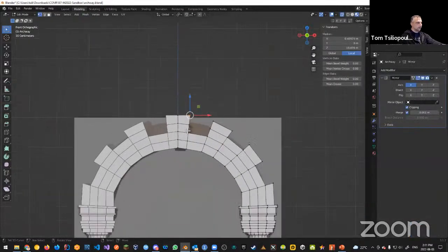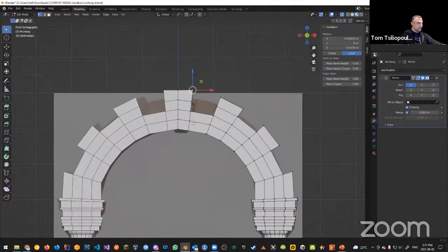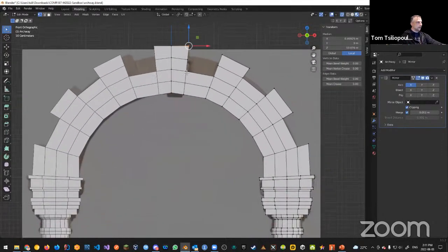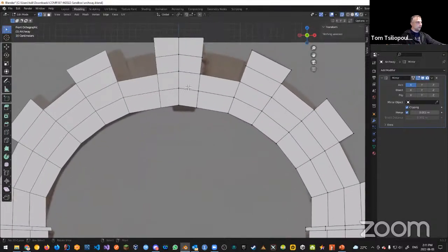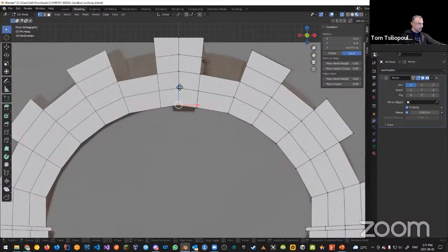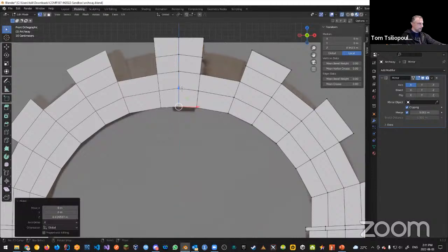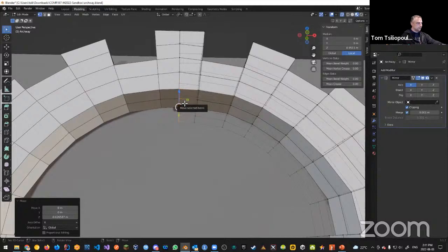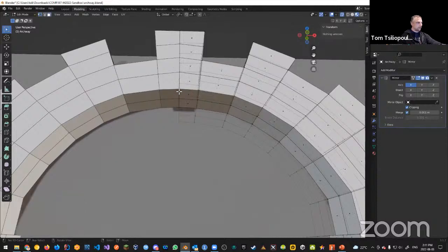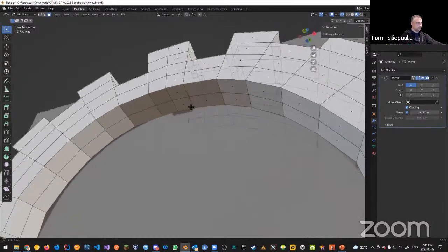We're almost done. So we want that bottom part of the keystone to be something like this as well. So what I'm going to do is deselect all, grab that bottom part and pull it in so that it is flatter. And we've got to be careful about how this is going to look, because if I want that extra part down here, which is kind of this part extruding outward, I need to extrude these faces, but we're going to have extra internal geometry when we do that, right?